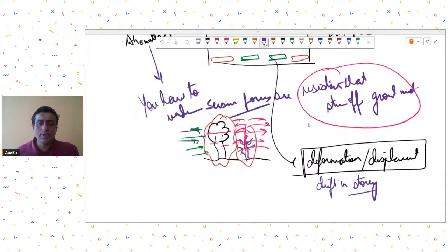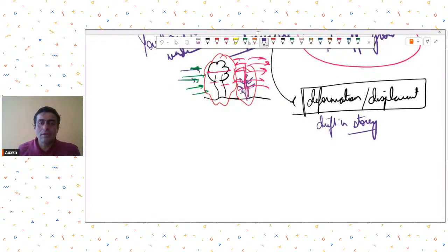Are you getting this point? Also, another reason why you want to control the lateral deflections is the P-delta effect, or the effect of gravity loads on your system which undergoes sway. If the sway values are large, the gravity loads acting on your system will have a greater impact on your structure.